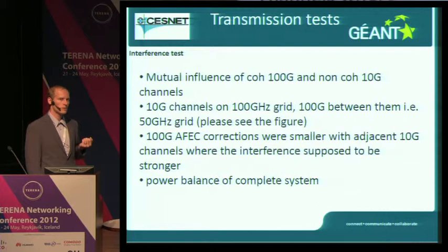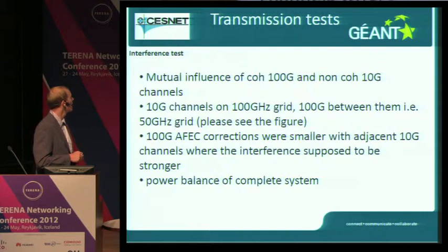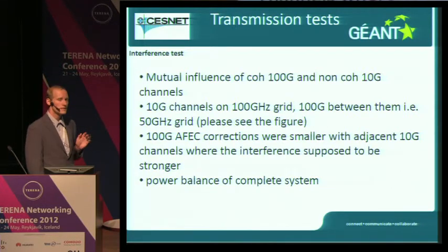As you pull out some channels from the line, the amplification gets bigger on the other channels, and also the amplifiers will work in a different regime, and they may have some other phase noise than before, so it could add to the coherent signal. So there was actually some mutual influence, and we would like to test it once again once we have a 100G system available.